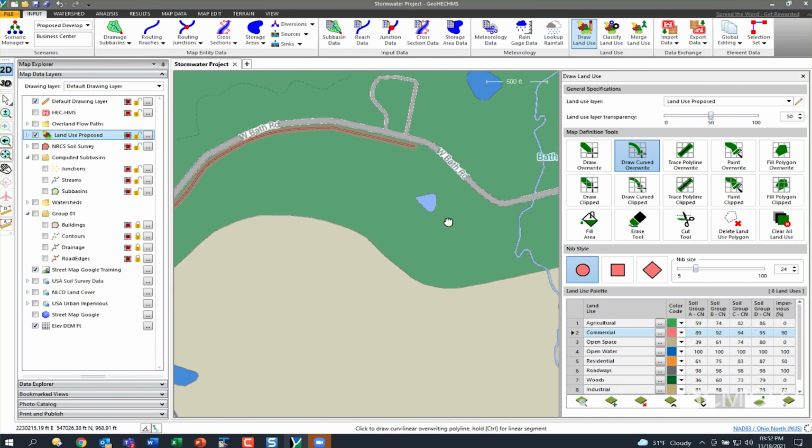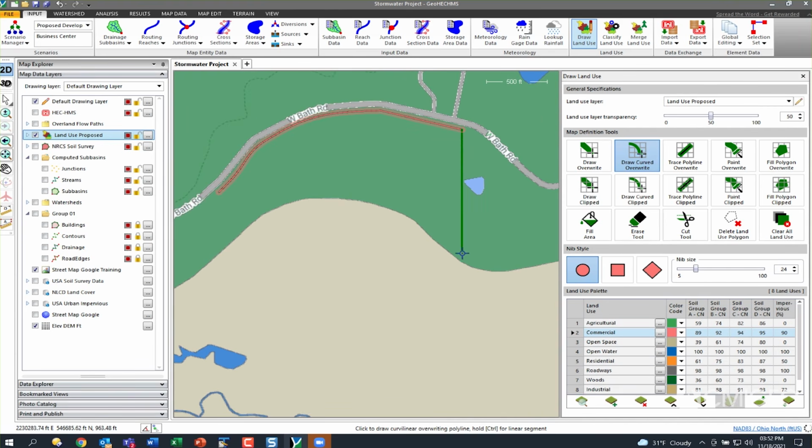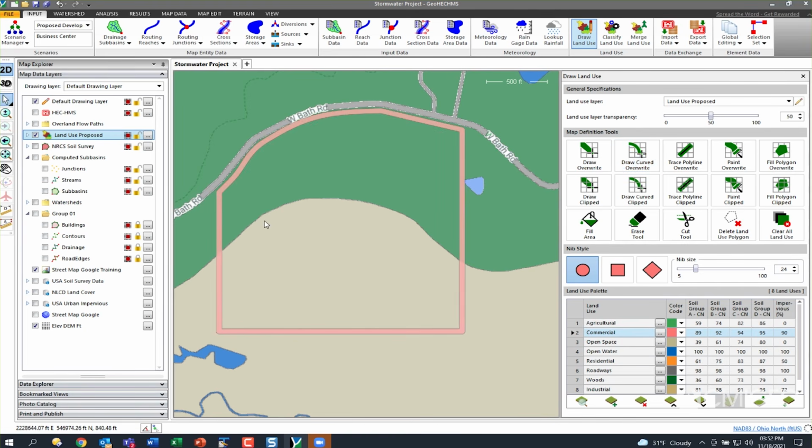Then I want to go south here, and I want to go in ortho, so I hold the shift key, take this over to, let's say, right there. Take this over. Now I want it to connect up to here. So what I can do is just put your cursor right here, click, and then click again. It closes on itself. Just right click, say done.